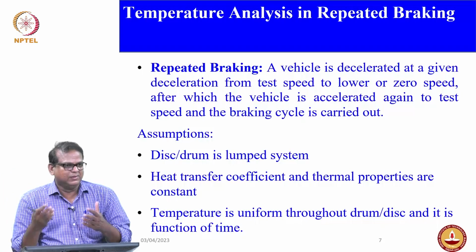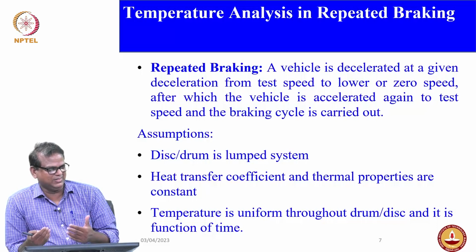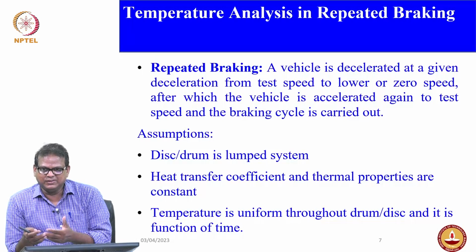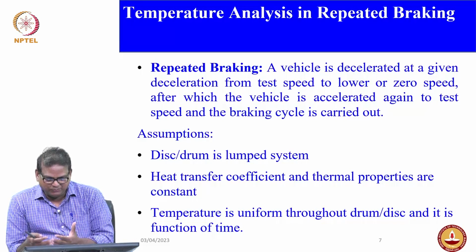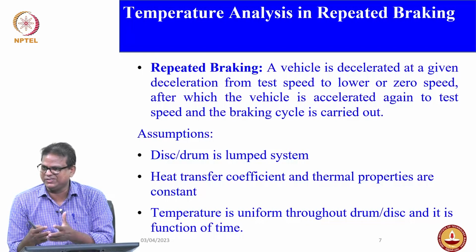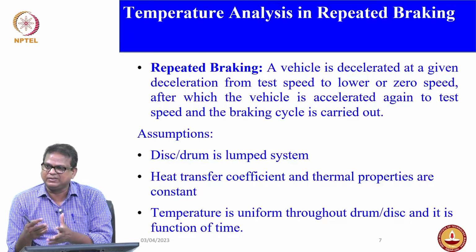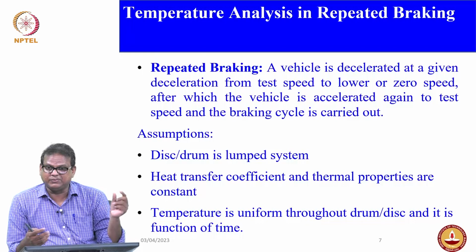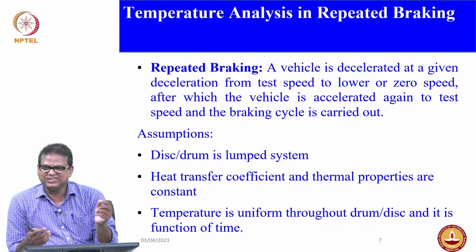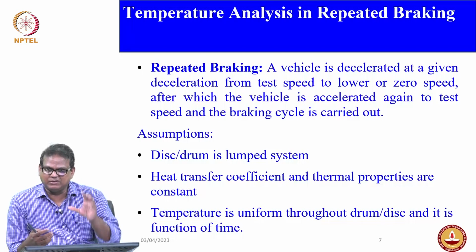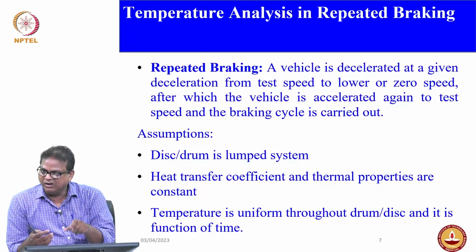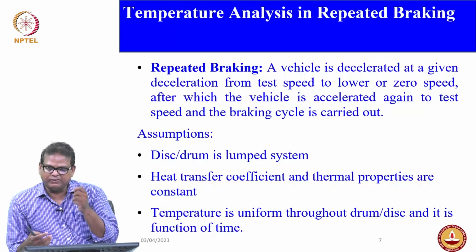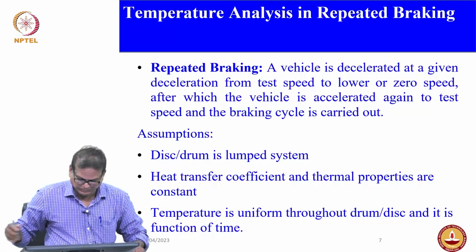By doing that, you are allowing the system cooling also, whereas in single stop there is no possibility for cooling. Since cooling takes place, obviously you would expect conduction, and apart from conduction, you will have convection also. That is what I discussed in the previous lectures for repeated braking. Remember h, the convection of the rotor, then convection of the pad. We found out the heat transfer individually for the pad and the lining also.